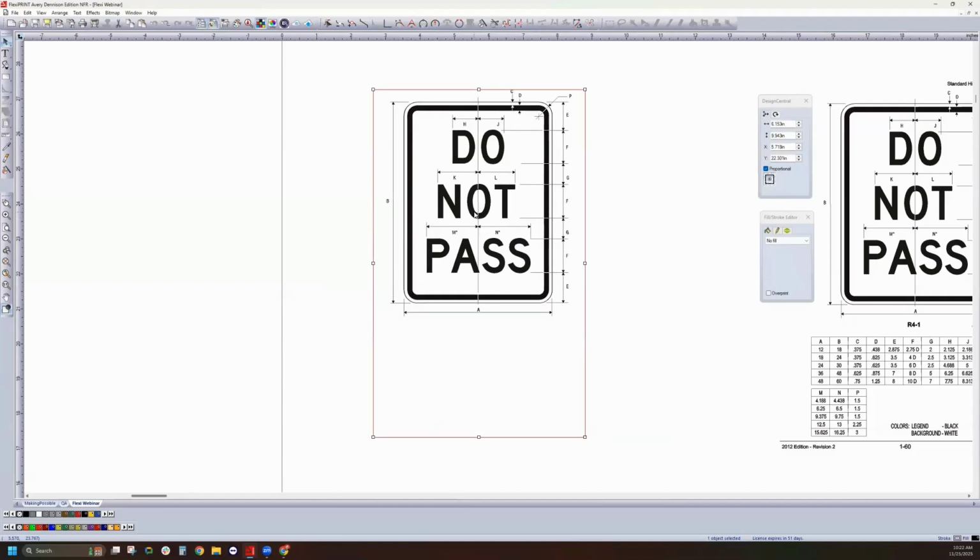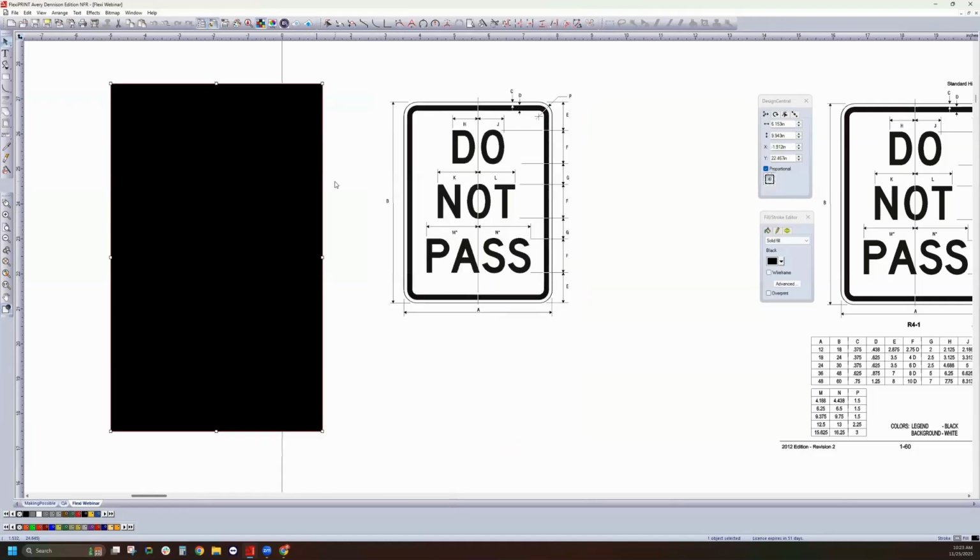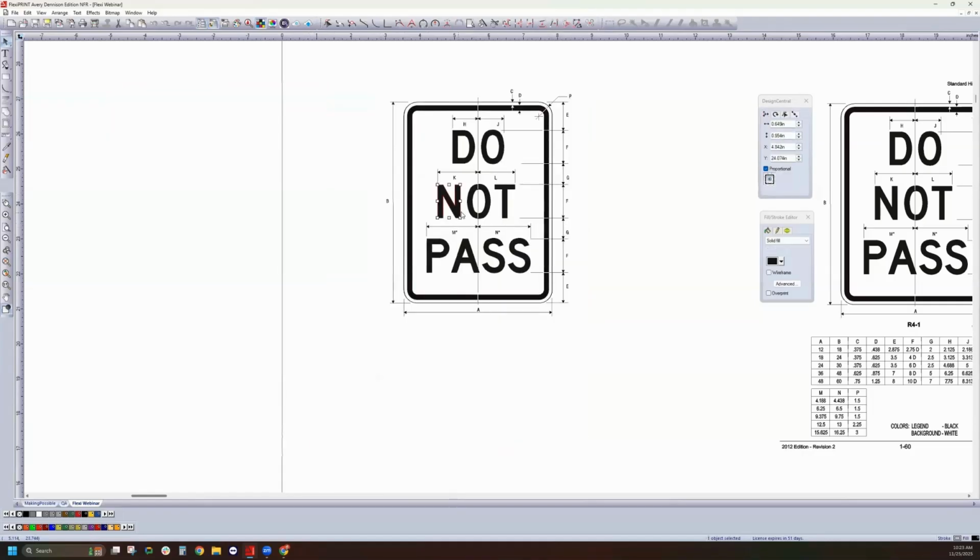Now we come to the part that's masked. Again, just like I showed you with the Avery Dennison logo, I'm going to right click on that and select unmask. I know that this is a masked vector because when it's selected, I don't have the bitmap option in the Design Central window. So I'll select unmask all. There's our black mask there, and then here are our vectors behind it. So we have all these measurement guidelines from the specification drawing that we need to get rid of now.